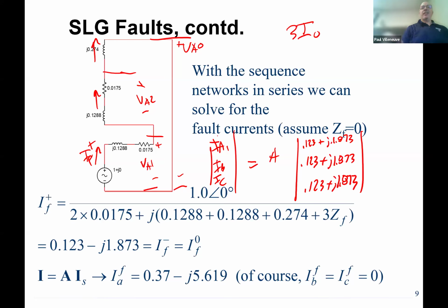So basically what they're saying is, what does IA or IF equal? Because it's 3 times the zero sequence current for phase A or B or C. So when you say 3I0, you're saying, what is a single line to ground fault current? But in relaying manuals, they just call it 3I0. They don't even say IA, they just say I0.